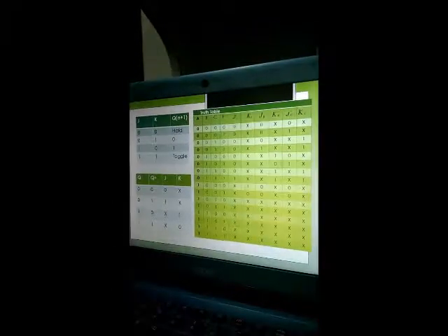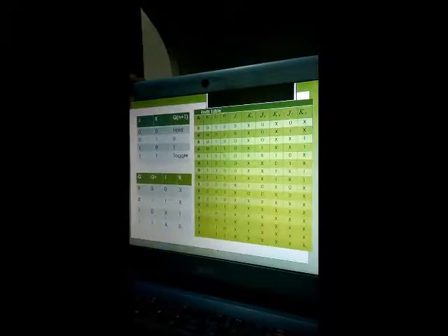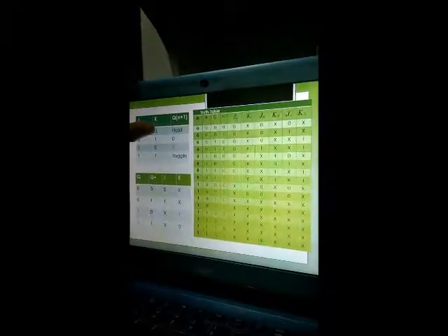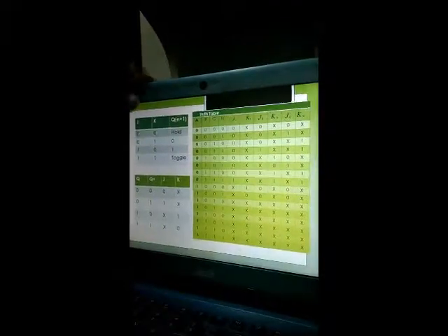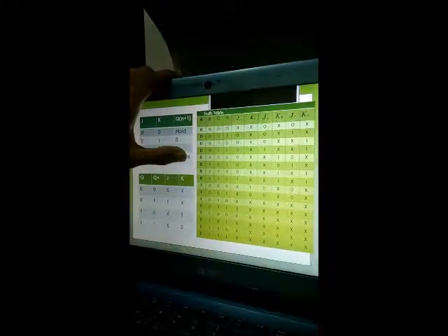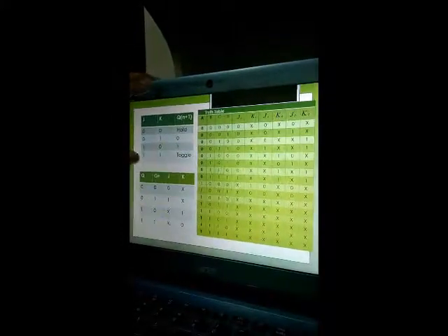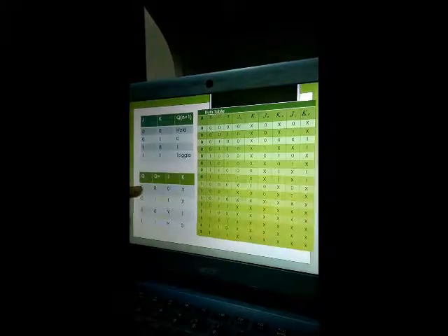Here are the JK properties. When the input J is 0 and K is 0, the output will hold. 0 1 will be 0, 1 0 will be 1, 1 1 will toggle the output. And here is the truth table as we created.